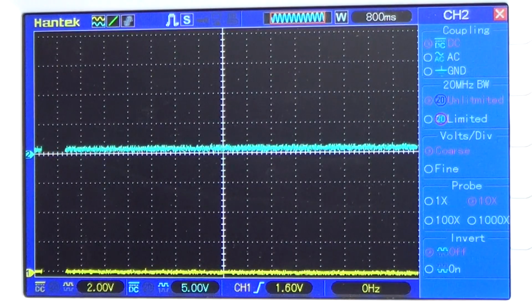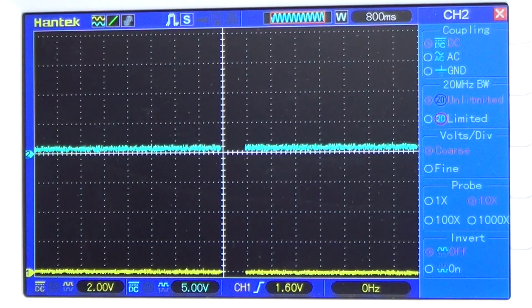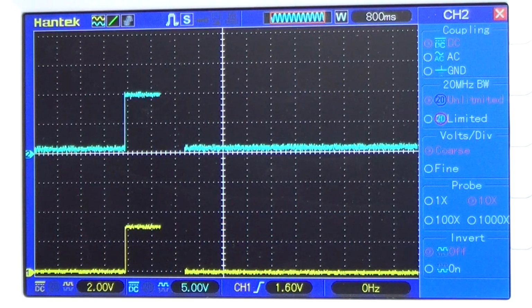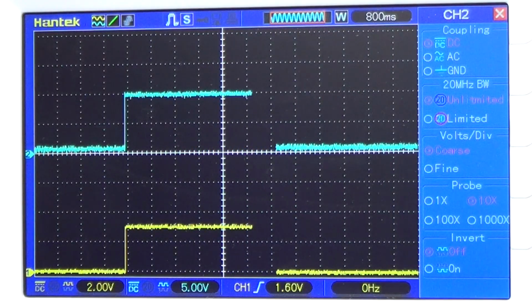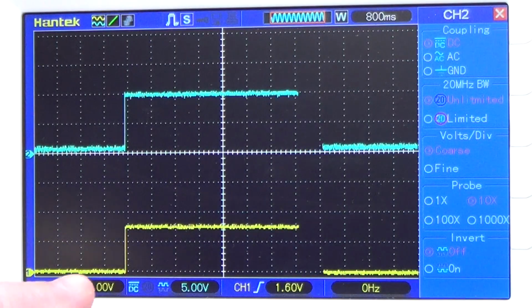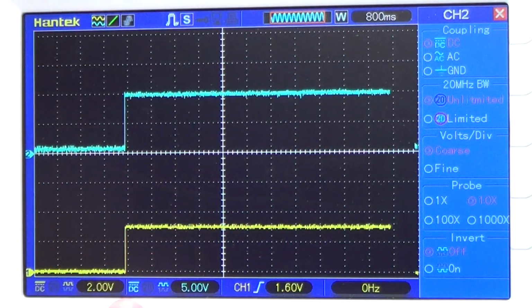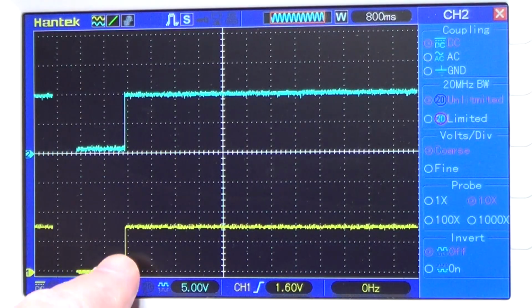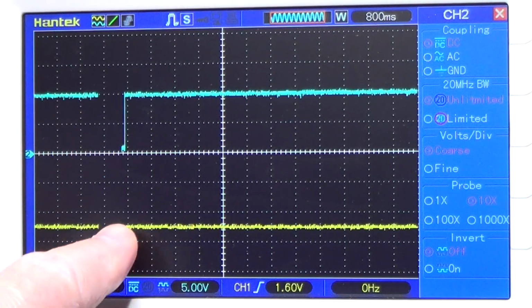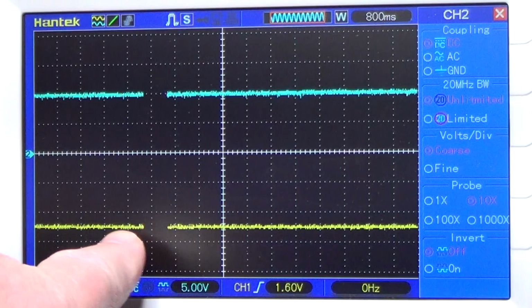I will also be keeping my finger on the pad to prolong the note enough to be able to measure its details on the oscilloscope. Here I just tapped pad 1 and I left my finger on it. You can see that both the notes and the velocity CVs have been generated. The notes CV seems to be a little over 3.1 volt, while the velocity CV is about 10 volt, according to the scales I have set on the 2 oscilloscope channels.